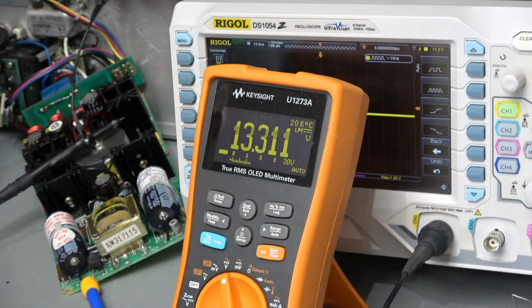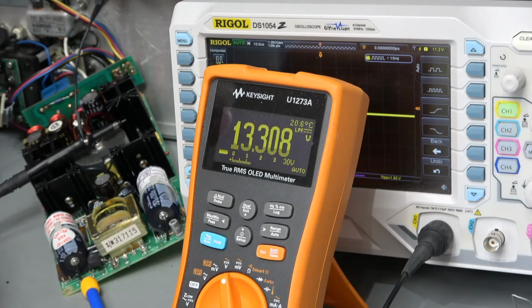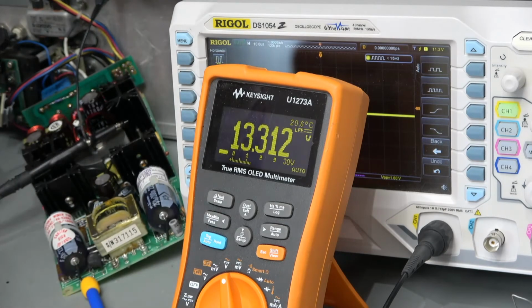So why is it that our two power supplies are behaving somewhat differently? Our old one, we know there's a fault on that, which cuts out after a while, but when it's not cut out, we can measure the voltages. We get 5 volts regulated, and then we get a sort of ever-growing voltage on the plus minus volt DC, and those are unspecified voltages, but guessing it's supposed to be around about 15 volts,